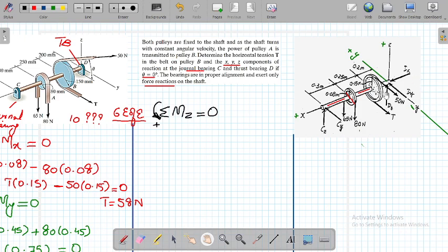Dx, Dy and Dz all pass through the z-axis, so there will be no moment. Cz is also along the z-axis, so there will be no respective moment. So the forces involved are the 50 Newton force, T, and Cy. Let's sum the moments about the z-axis.